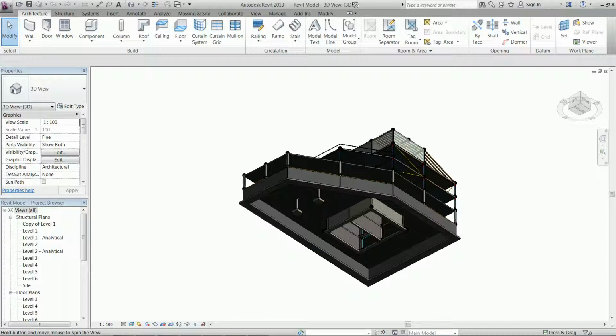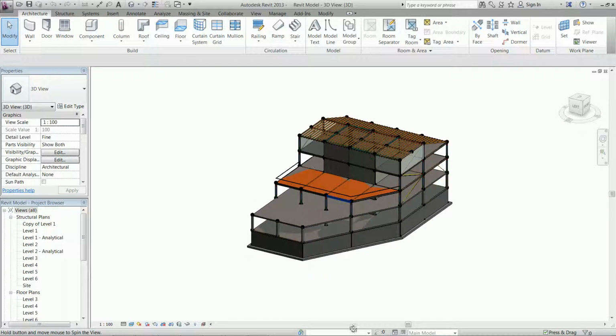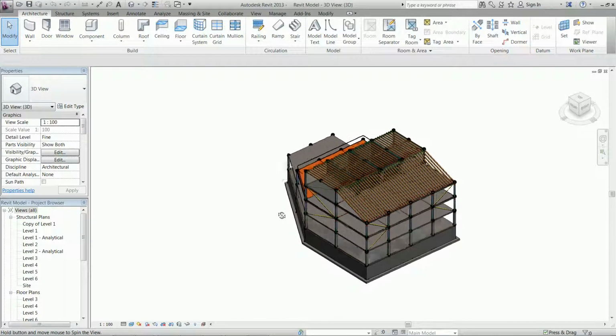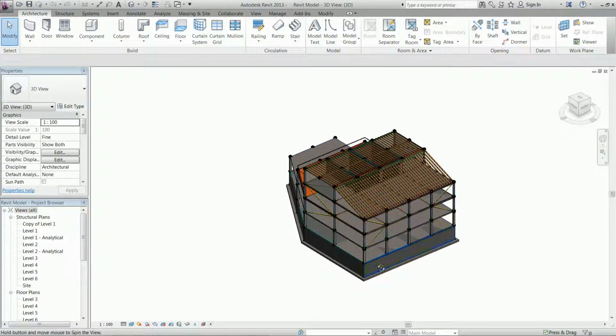As you can see, it is a multi-material building. We've got all the foundations in the form of strip, foot and spread. We've also got a buried reinforced concrete earth retaining wall. We have the concrete columns supporting concrete slabs on the first two floors. And we have the steel for the top three floors in the form of columns and beams and also bracing.